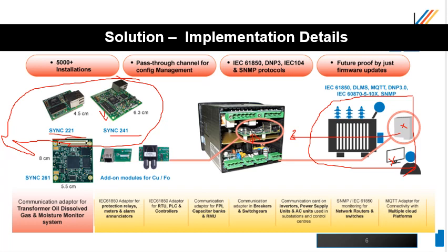and then this 200 series OEM module will directly convert that onto the Ethernet port. This Ethernet port is exposed outside, and this Ethernet port can have 61850 or DNP3 or 104, etc. on this port. So this port is exposed outside, and that will have the latest protocol.